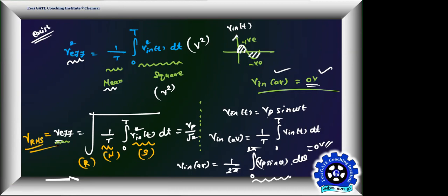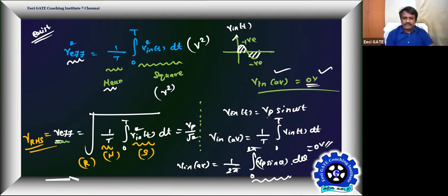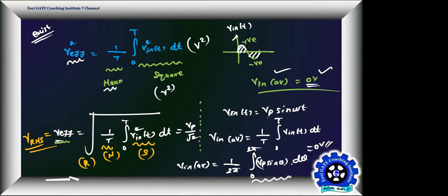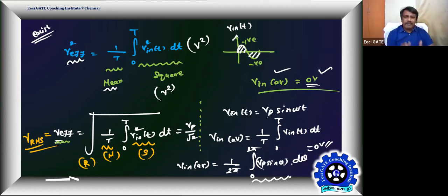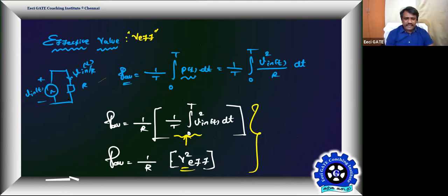All of you getting it? Swati, getting this? Dinesh, following this? Okay, so that's a convention. We remember RMS and forget V effective. V effective makes a lot of sense, but VRMS talks about the mathematics of how to get the effective value of an AC source. RMS says square the signal, apply the mean, and then apply the root. Then RMS gives the effective value of an AC source, with which one can quickly find the power delivered by the AC source.